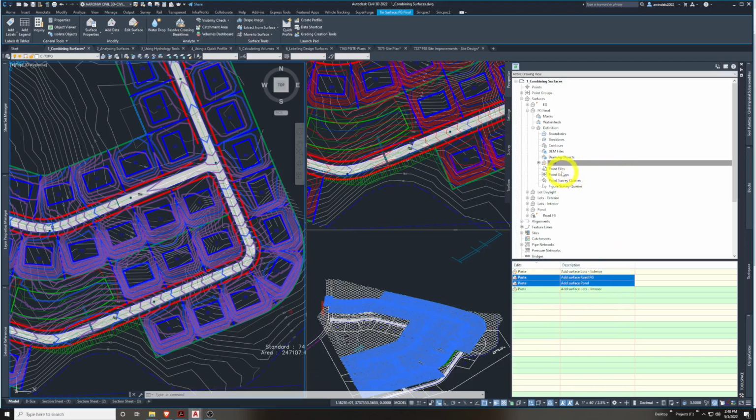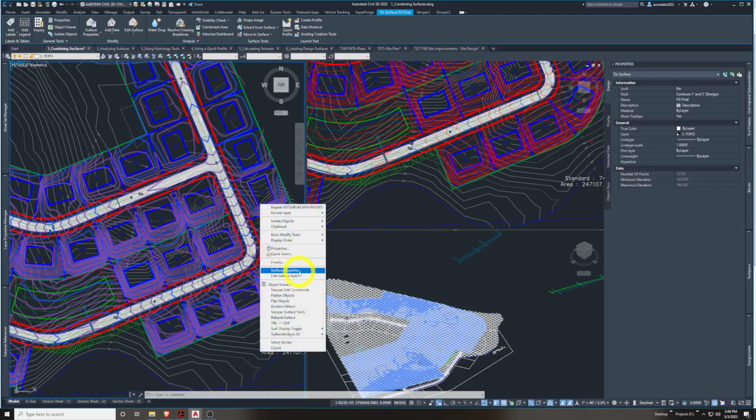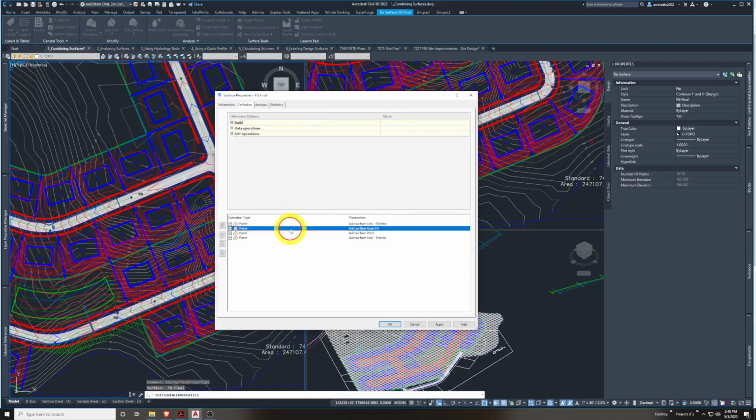Here they can be deleted out fully and out of the surface definition. Think of that as a permanent move. If I go this route and I have it selected, I'll go this right-click method to properties instead of here. Just multiple options always. This is more of a temporary one. We could delete them out of here, remove them by right-clicking, or if we just click this checkbox, it would only temporarily remove that edit operation. We could add it back later with our checkbox radio button.